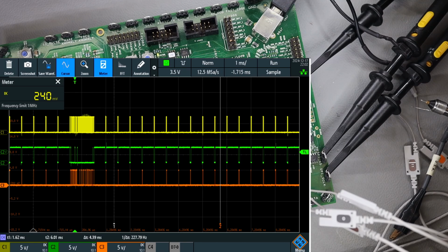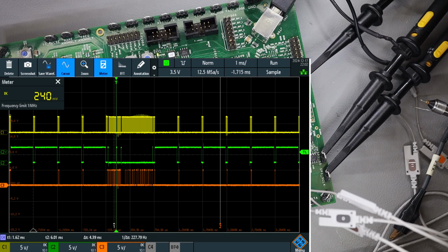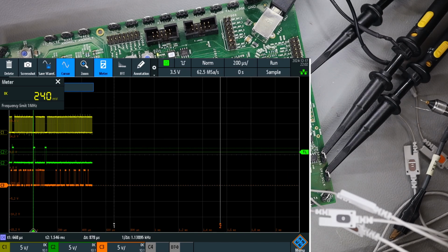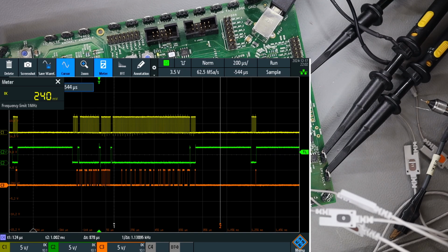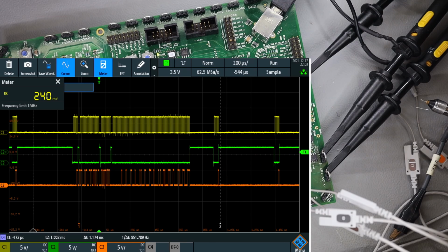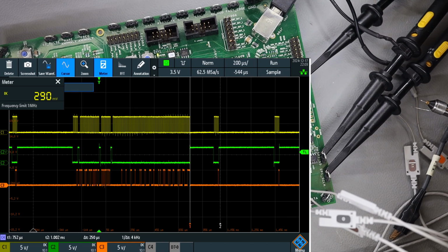It was easy to define a criterion of greater than 50 microseconds. It means we are looking for just a slightly larger packet. So the oscilloscope is triggering on this packet because it found no negative going pulse normally, because oscilloscopes even have dead time. We can talk about that later, but normally it finds this pulse after a long period of time. So it finds this first pulse. That's why you see the trigger is right here, because the time from this place to this place is greater than 50. This is how it finds it. If you want to trigger right here, then you can increase the time. I'll show you how to do that.